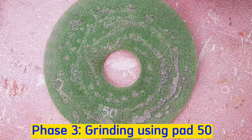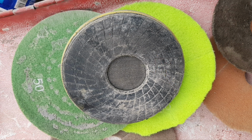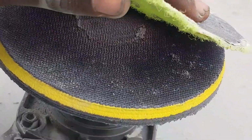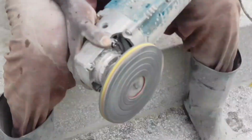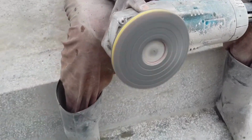The third phase is grinding using pad 50. And by the way, here is how we change from one pad to another. Let's say you are changing from pad 50 to pad 100. Remove this pad 50 like this, then fix the next pad you want. Hit it to make sure it fits properly. Power the grinder and do the grinding process.